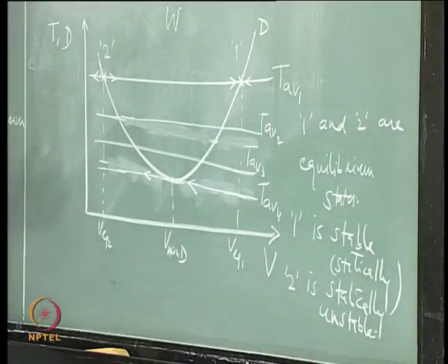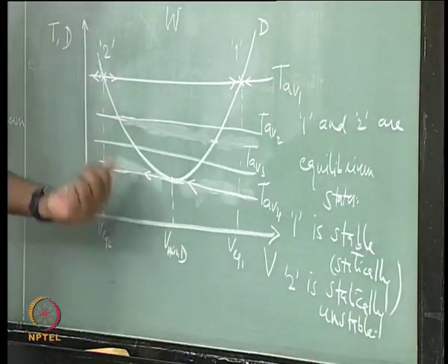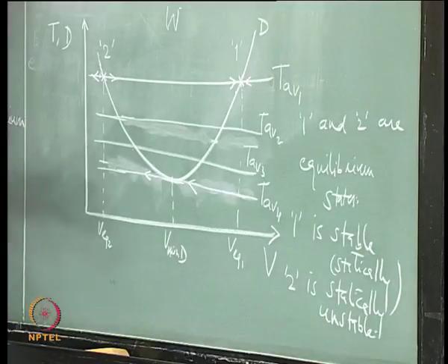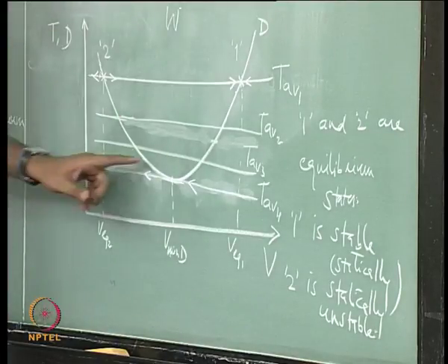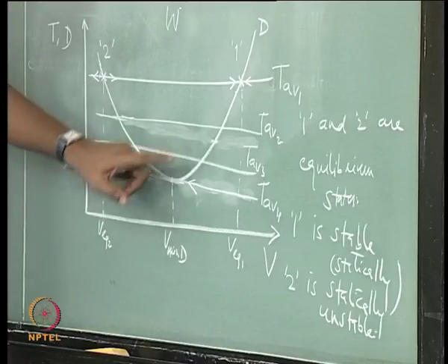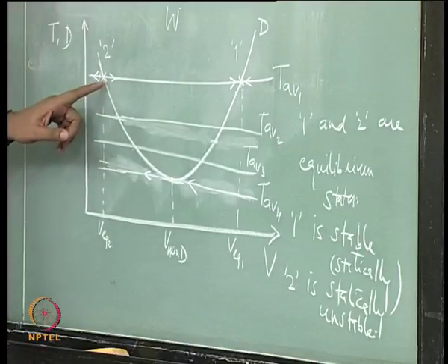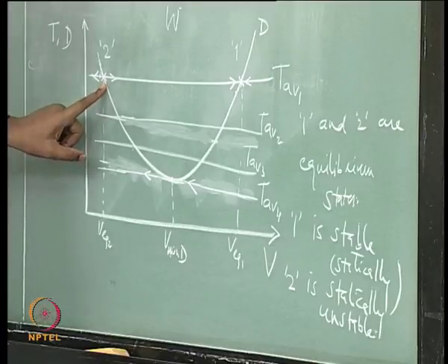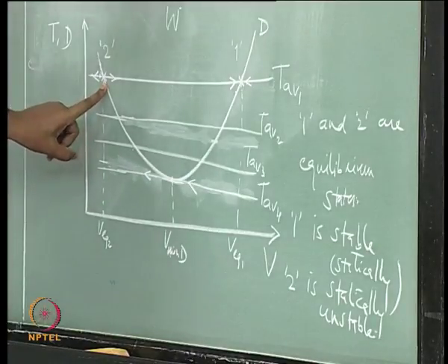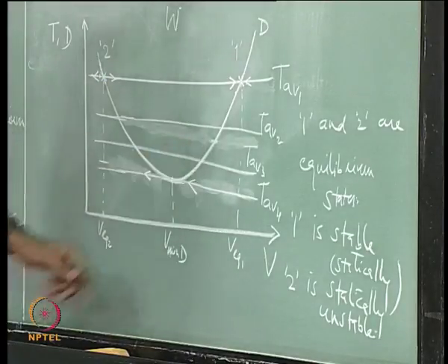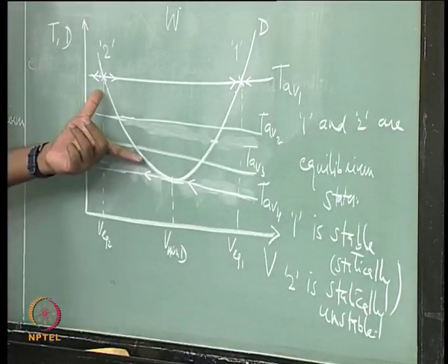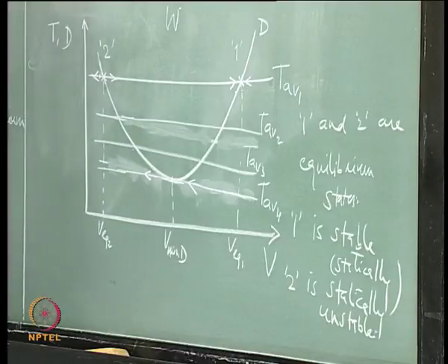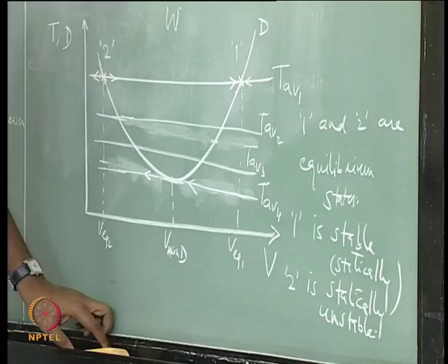But in reality what this tells us is that this whole part of this curve, where we can find several trim points by changing the thrust available, is not available for flying, they are all unstable, and on this side it is all stable. In reality this is not what happens, and we will talk about it when we come to dynamic stability.